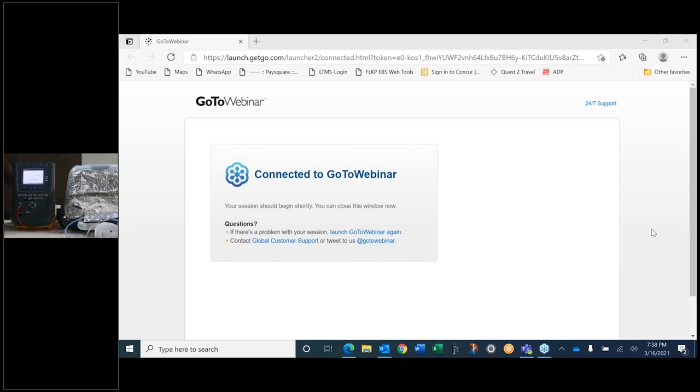So to test the touch current, we are going to press the microamps button which is available on the equipment. Okay. Please note that we are going to do AC plus DC right now and we are going to put our alligator clip to the aluminum foil. Okay.